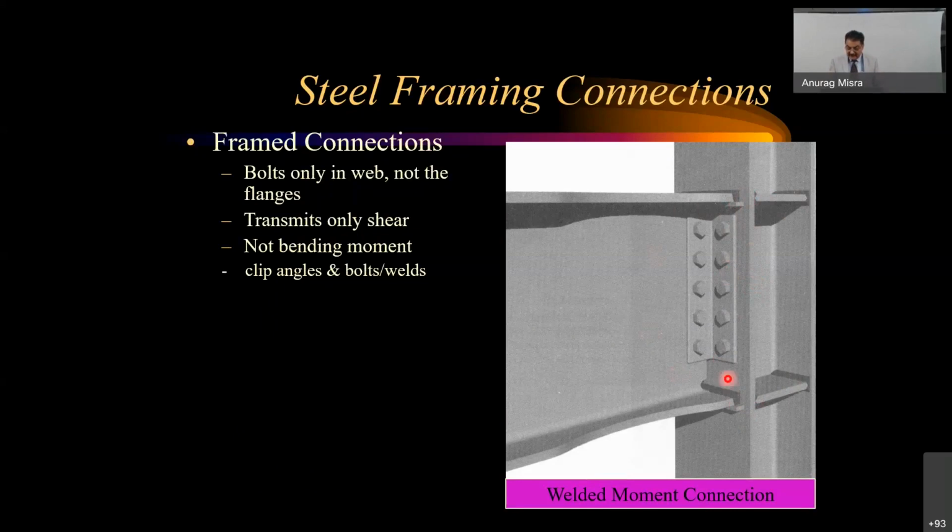So a typical section I'm showing here that you can have, and there could be certain members here also in the L shape, which could be connected to this bolt and this bolt, this plate, for taking all the moment which is coming onto the joint.